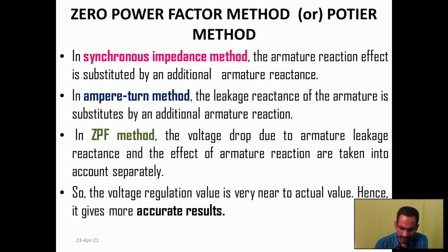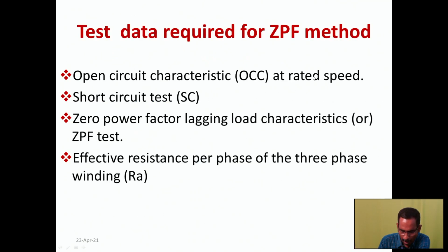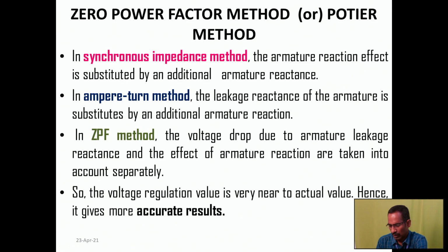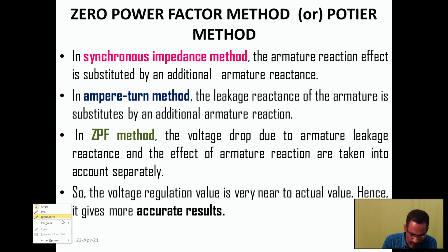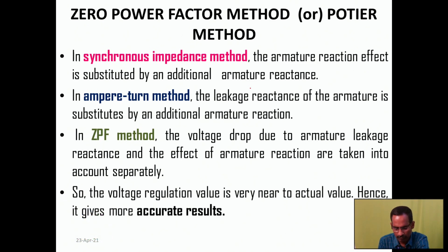In the synchronous impedance method, the armature reaction effect is substituted. In the MMF method, the leakage reactance XL is considered as an armature reaction effect. But in the zero power factor method, the voltage drop due to the armature leakage reactance and the effect of armature reaction are taken into account separately.